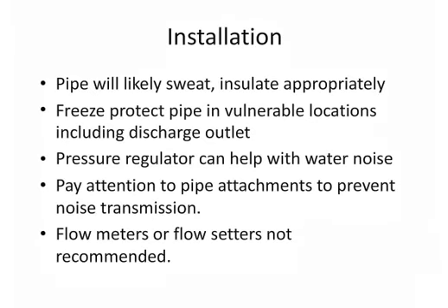Installation. Well, those pipes are typically going to sweat depending upon your particular location, so you want to make sure you fully insulate them, and always bear in mind, if you're in a heating dominant climate, freeze protect that pipe. Remember, it's not just a supply pipe. Now you've got a discharge pipe. So if you're going through a crawl space or some area where it can be exposed to low and freezing temperatures, you want to make sure it doesn't freeze up, because then it's going to shut down because it's not going to get the water flow it needs.